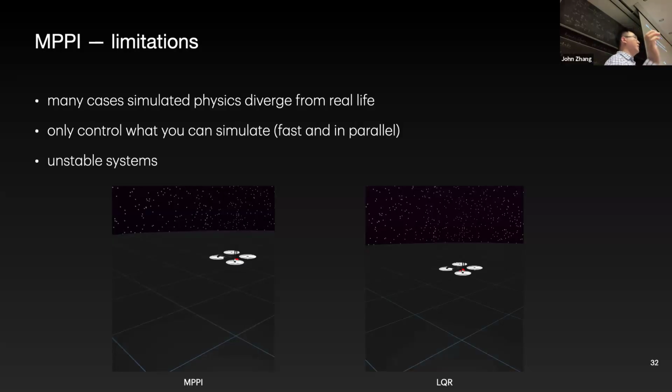Or you can do a multiple shooting or collocation type approach, where you simulate the unstable dynamics for only a couple of time steps, or maybe a single time step, and solve the general nonlinear optimization problem. There, you don't have to deal with the unstable dynamics.